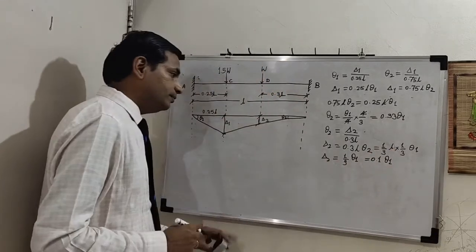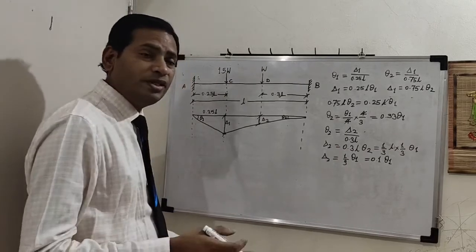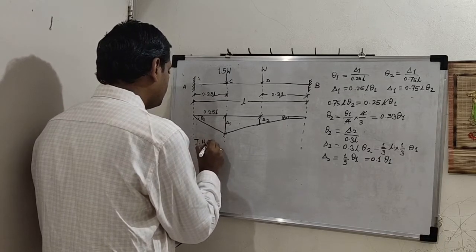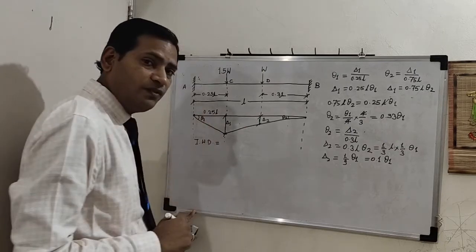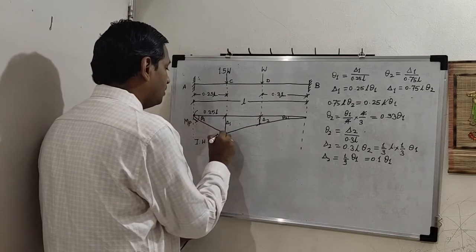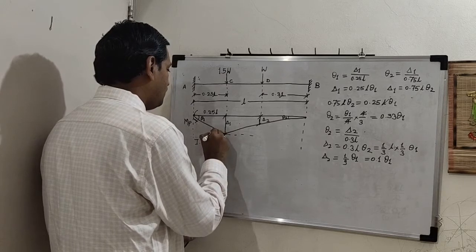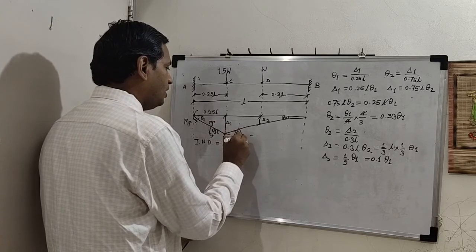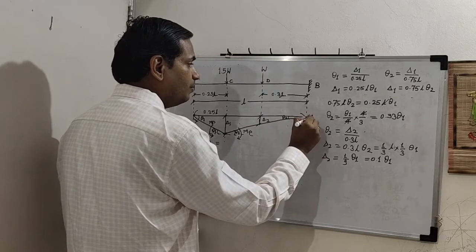Okay. Now external work done and internal work done. We again have to go to basics. So internal work done is equal to, where are the hinges? One is here because this is a fixed end. So here is MP. Another is here. This is theta 1 and MP. This is theta 2 and MP. Here is one last hinge and its corresponding MP.